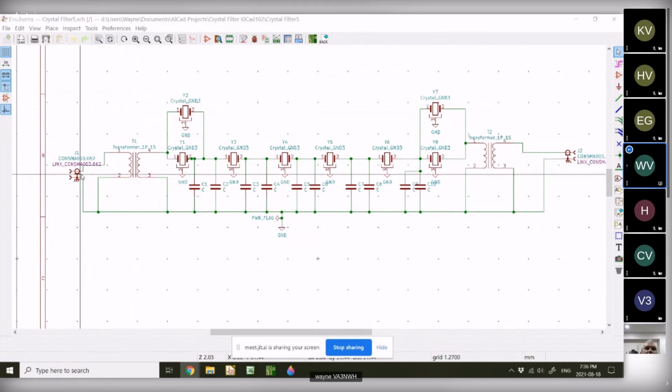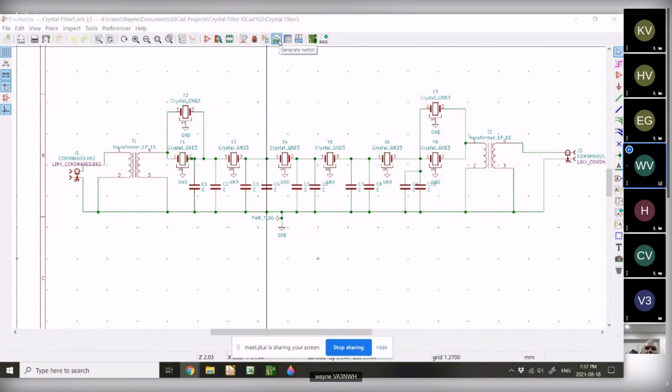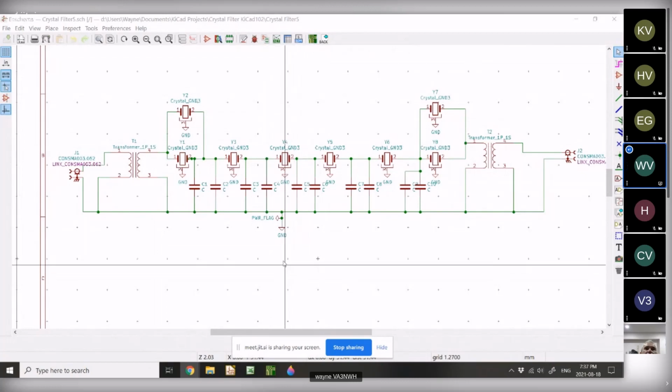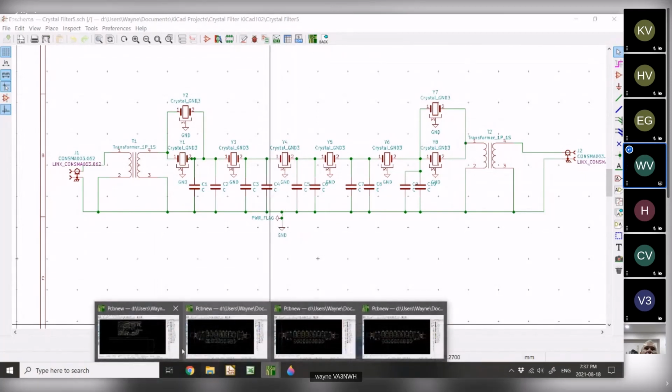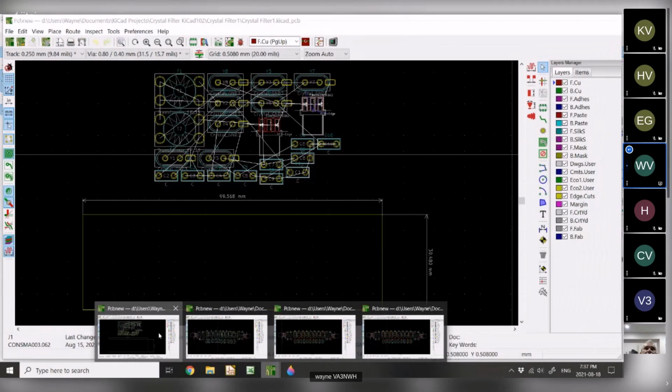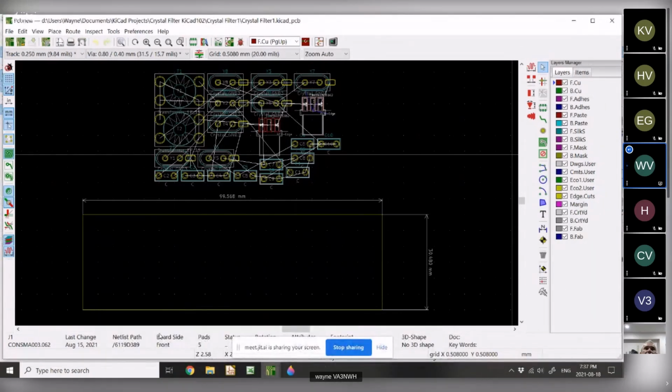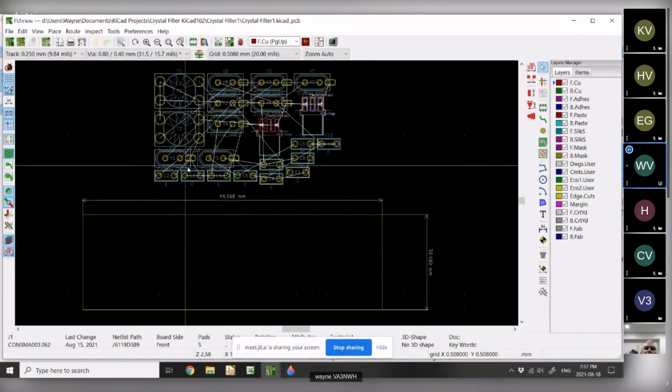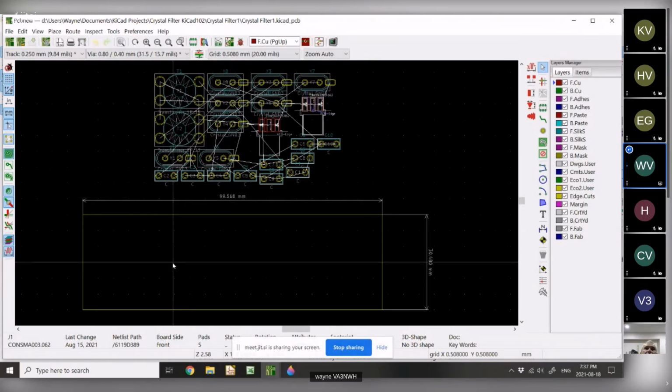The very last thing that you do after you're sure that your picture's okay is you generate a netlist. Okay, and then you can actually launch the PCB function from here. I've already got it up, so I just have to find it. This is what you would see when you come in. Actually, you see a blank screen. I'll explain why I put this up here in a moment. I've just taken the first 2 steps of building it.